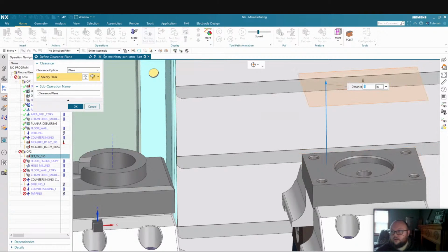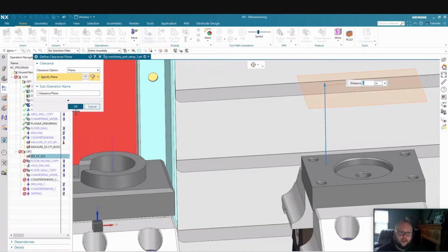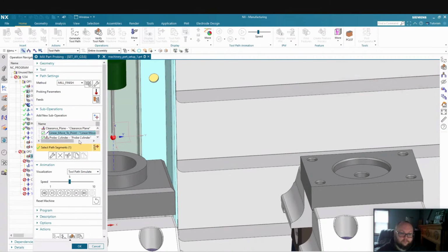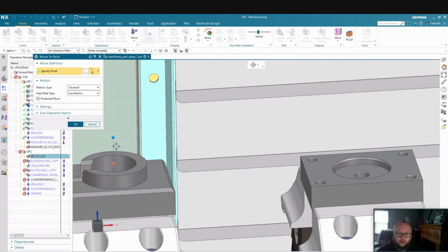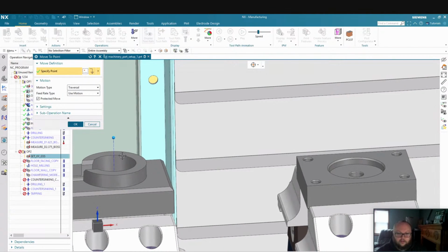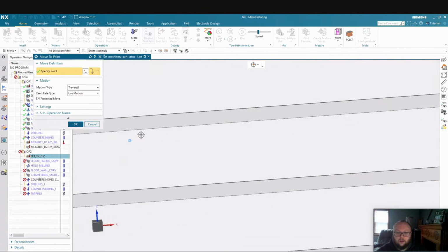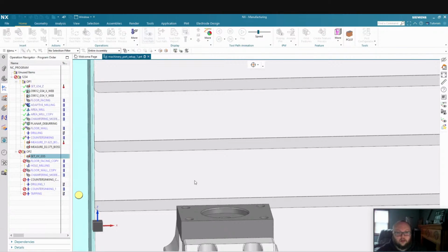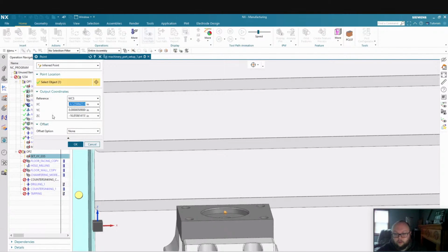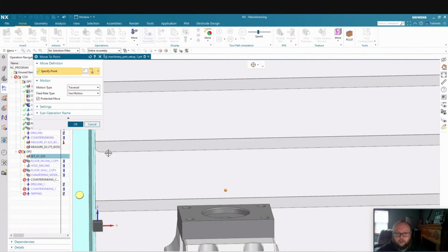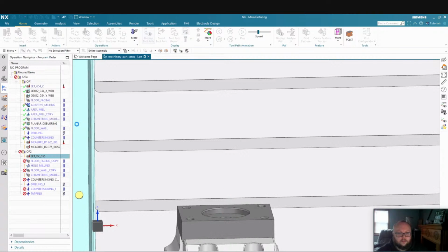So let's offset that 3 inches again, a value I like to use. Linear move to point. Of course, we're not working on this first part anymore. We're working on the second part. So I'm just going to go ahead and reselect a new point. And again, I'll do the rectangular offset, just moving my Z0 up 1 inch from the finish face.